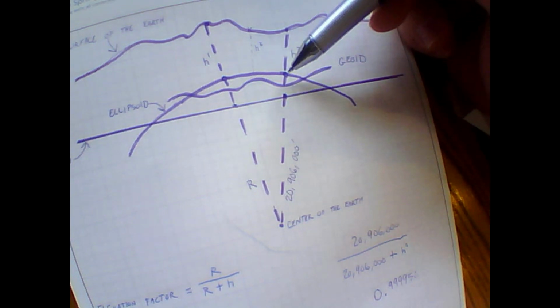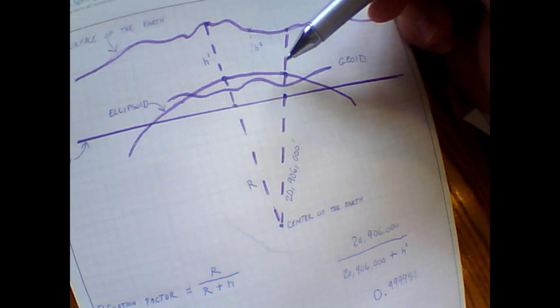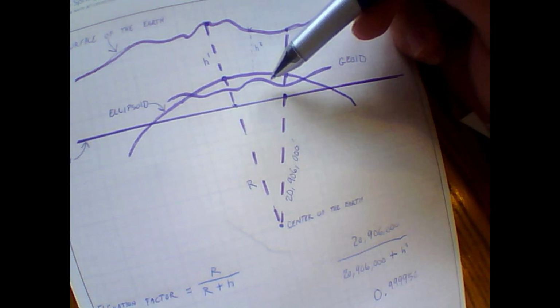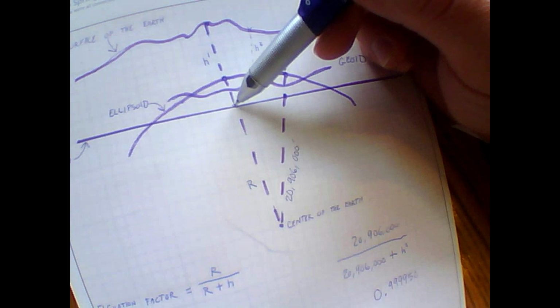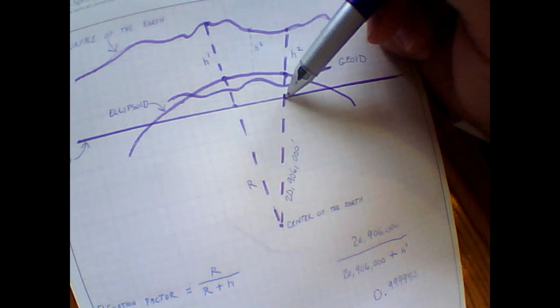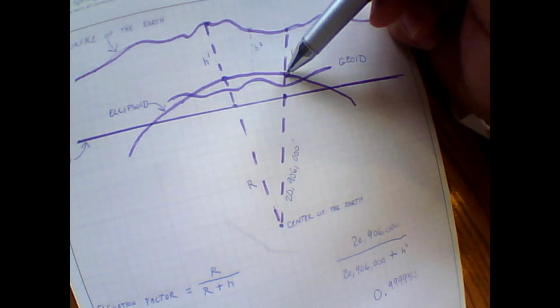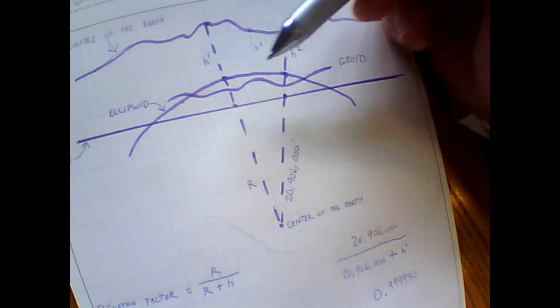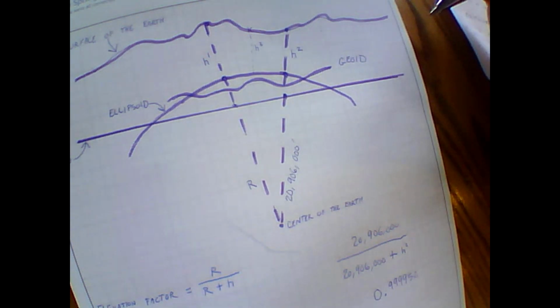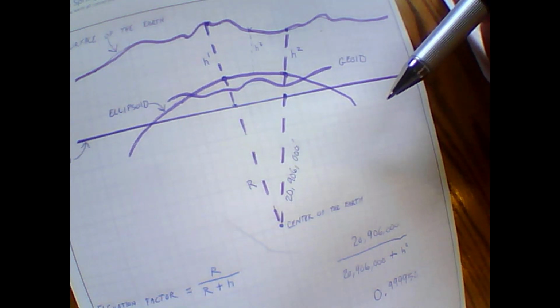It knows where your grid is. It knows where your ellipsoid is. It knows where you say you are on the ellipsoid. It's automatically calculating this. What it's doing basically in rough form, it's taking your grid distance and dividing it by your ellipsoid distance, your geodetic distance between these 2 points. And then you're coming up with that number, which is going to be less than 1. And that's the scale factor.